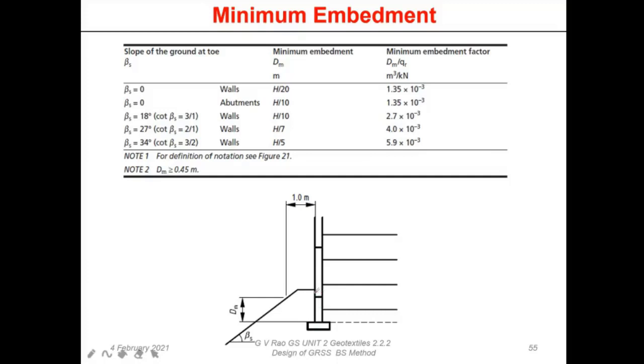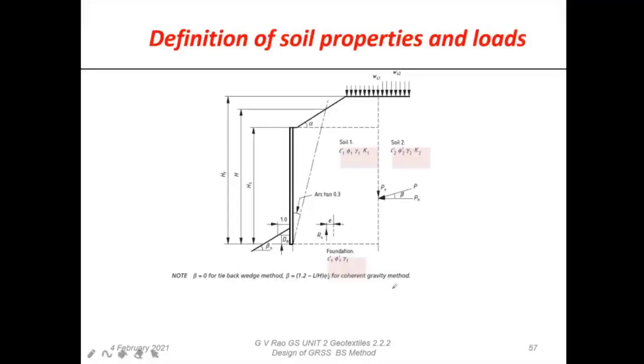because if this entire depth is going to be more now, the wall has to start from that level. It's not only the portion above, we are going to have the wall in the portion below also. That means we are going to have all the reinforcements, which is going to make it expensive. So the abutment depth is going to be taken as the minimum abutment depth based on the code. Okay, we'll just close after a few minutes.